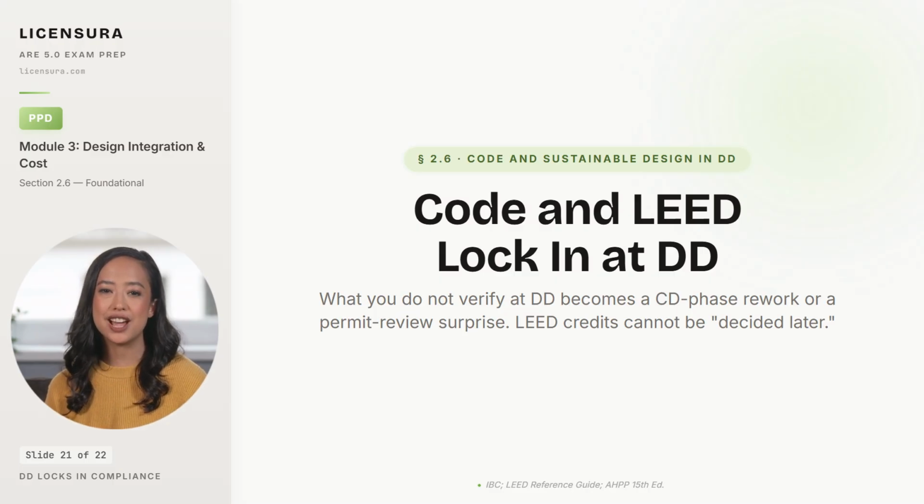LEED credits are even less forgiving. You cannot decide later. Daylighting credits require window sizes and locations that exist at DD. Energy credits require an energy model with the actual envelope and MEP selections.